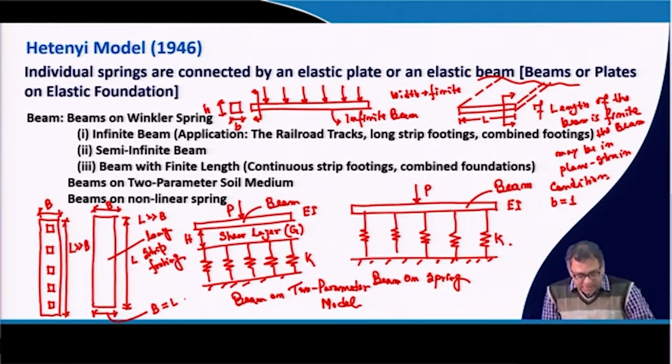Because you can model this type of problem in two ways. In the first case, if it is an infinite beam, the length is equal to the length of the foundation and the width will be the width of the foundation, simple. In the second case, the width of the foundation will be the length of the beam, but as it is under plane strain condition, because the distance perpendicular to the length is much longer, we have to consider a unit width, B equal to 1.